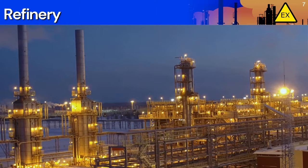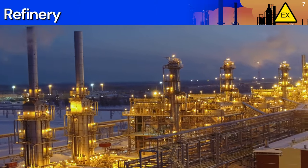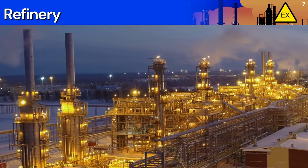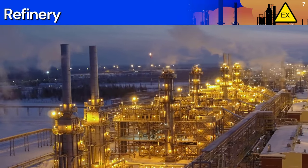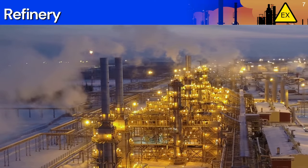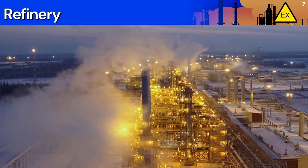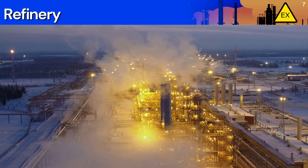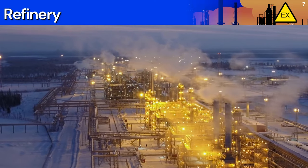Refineries and petrochemical facilities present even greater challenges to explosion safety. Large quantities of flammable materials handled at high temperatures and pressures will warrant very large classified extents. Coupled with a large number of potential ignition sources, including unprotected fire heaters and vehicle traffic, a refinery classification can be a difficult challenge.